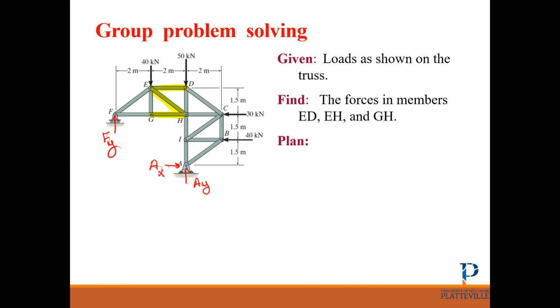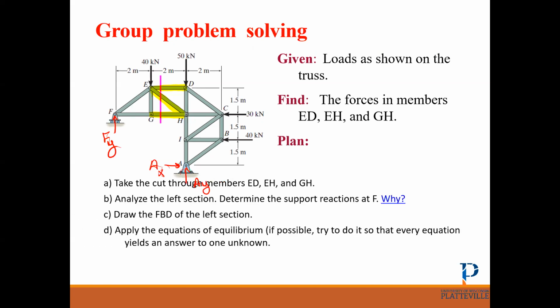So the first step, where to cut. The next step is which part you want to analyze. And the third step is apply the equilibrium equations. All right. So stop the video and then draw a free body diagram for the left side and apply the equilibrium equations. Then we're going to check the answer together.